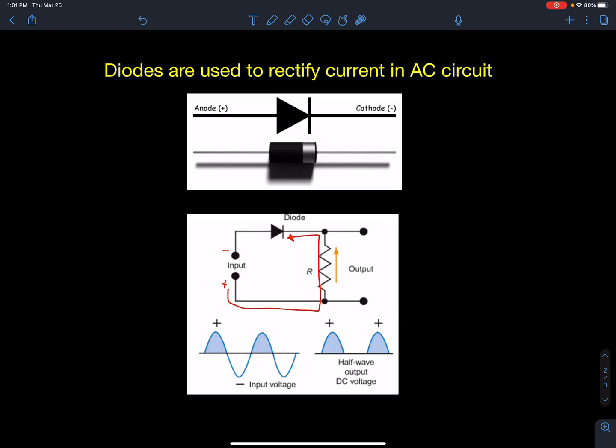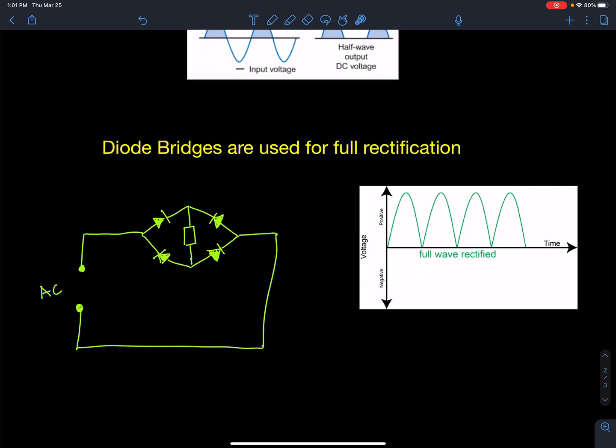Well, what we end up doing is we make a sneaky combination of diodes. So let's say this is my device, and the device wants current to flow downwards. The way I connected these 4 diodes always makes sure that current will flow downwards through that, despite the fact that the AC current is changing.